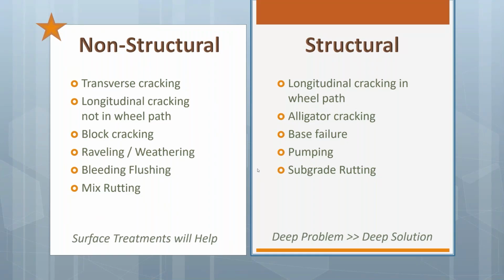the pavement structure. So the longitudinal cracking in the wheel path, that means that the traffic loadings in the wheel path are showing up as, hey, this pavement wasn't strong enough to hold up these loads, and it bent until it broke. And so now we're seeing those cracks. We might see alligator cracking or severe fatigue cracking. Everybody's familiar probably with that term. It might be that we have base failures. That could be something under the asphalt layer that's not so good.